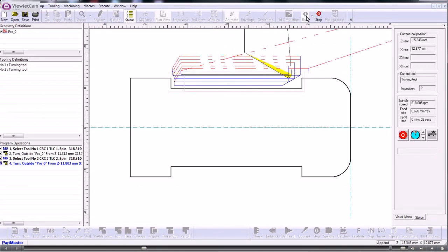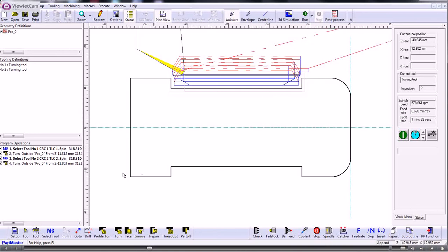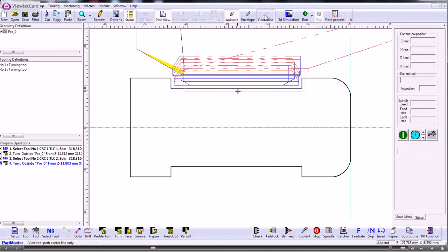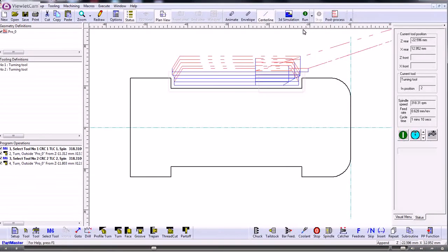Having changed the tip geometry, obviously now we could go back into that second tool path and change the working envelope so that it only moved to clear out the material left by the first tool. So if we want to go back in and change that, we double click the entry and then change the tool path to here. Switch it into centerline mode. So the second tool coming in from the left is only working on this area here. So that's one method of machining that groove.